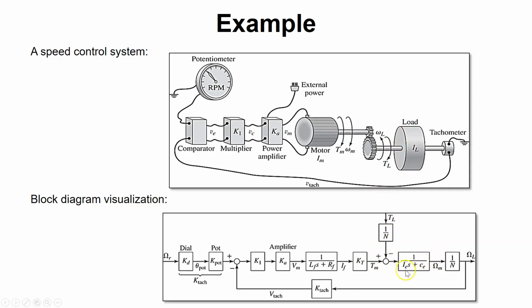And in the shaft you have an inertia and you have a viscous friction element, or a rotational damper due to lubrication of the shafts with lubricant. That will generate an RPM for you if you integrate it, and then that RPM is multiplied by the gear reduction to give you omega of the load.